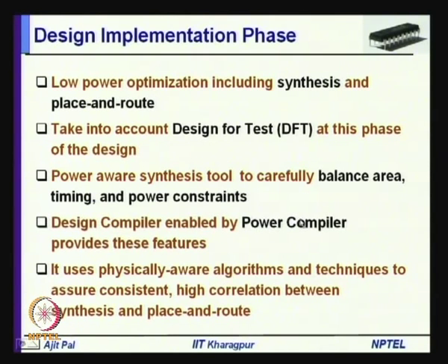What is done in this Synopsys tool? They have used Design Compiler enabled by Power Compiler. So, the Power Compiler is the addition which will take care of the power intent implementation. That means whatever low power techniques that we implement, that will be taken care of with the help of this Power Compiler.